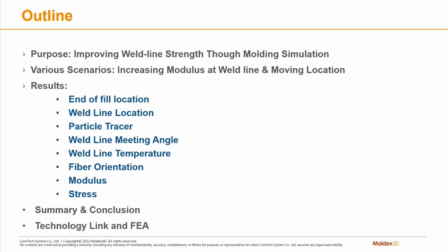We'll look into various scenarios surrounding that, and we'll look at the various results inside Moldex3D, like end of filling, weld line location, and more importantly, the particle tracers. So not only can you understand the location of the weld line, but also the physics behind it. We'll take a look at particle tracers, meeting angle, temperature. This will help you understand what those results mean, and also fiber orientation.